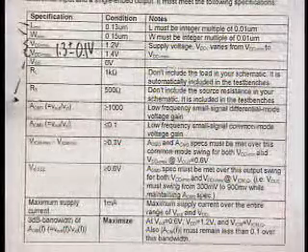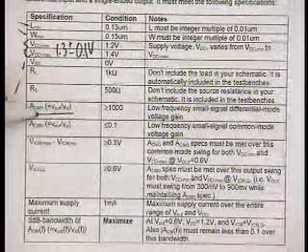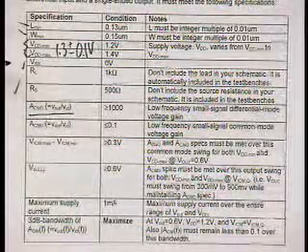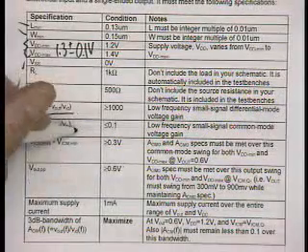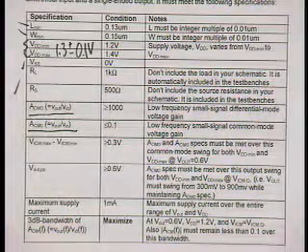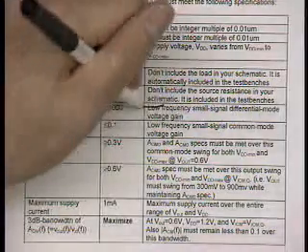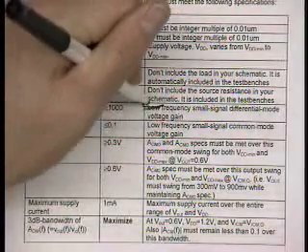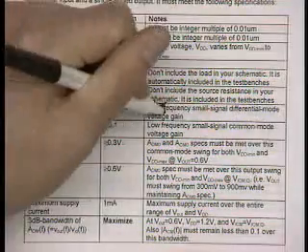So, getting back to this, so that's RS. You have a spec for the low frequency voltage gain, which is basically the DC voltage gain. And you also have a spec for the common mode voltage gain. Now the common mode voltage gain, and I'll talk about this a little later, is actually not just the low frequency common mode voltage gain, it's the high frequency common mode voltage gain as well. So this is wrong here. This should say high frequency. It's high and low frequency.